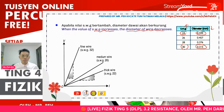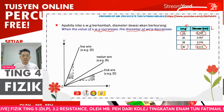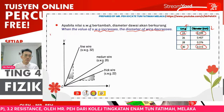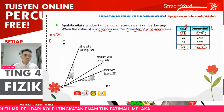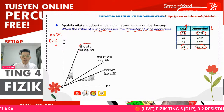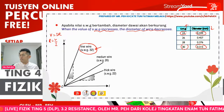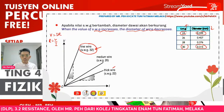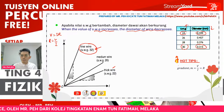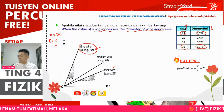Okay, so here this is the graph V against I for different sizes of wire. As mentioned, V equals IR, so R will be V over I. That means the gradient of the graph shows the resistance of the wire. So the fine wire, with the higher SWG value, shows higher resistance. This will be vice versa for the thicker wire, just as I mentioned already. So the gradient of the graph V against I shows the resistance.